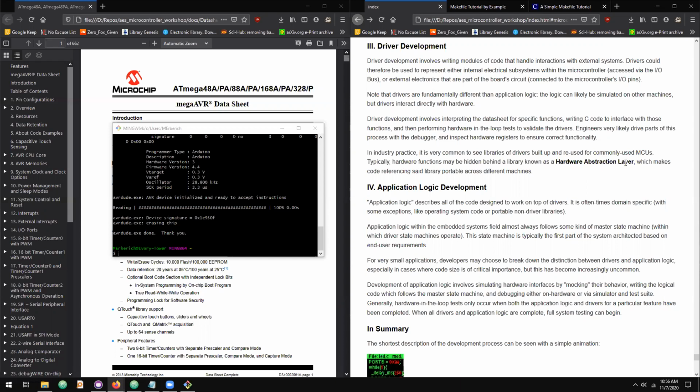So oftentimes, if you're working with the Atmel chip families, then Atmel will provide a library that they develop themselves for this purpose. As a hardware abstraction layer, specifically Atmel's is called the ASF, or Atmel Software Framework, and they provide drivers that run across a certain number of their chips.